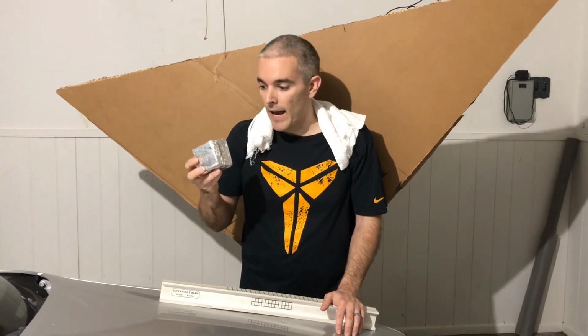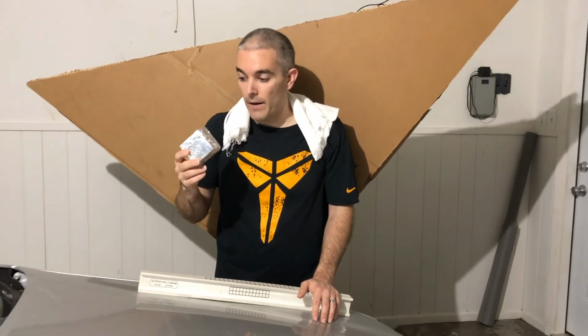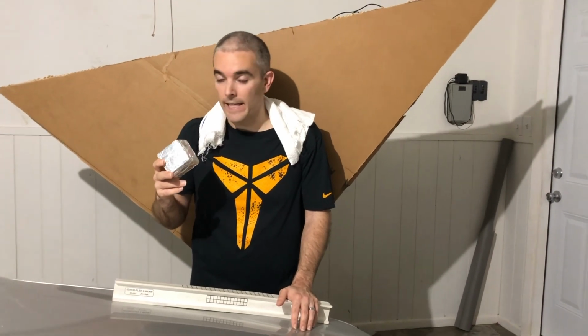So, we're dealing with our stress cube, and our stress has three-dimensional attributes, right? We have normal stress and shear stress in the X, Y, and Z planes. Now, we can simplify this a little bit. So we say that for many cases in engineering, we'll have the opportunity to use what we call plane stress. So what is plane stress?